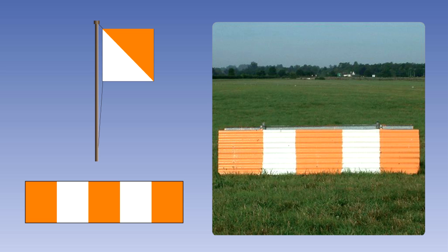At intervals along the boundary of an aerodrome, orange and white stripe markers are used to delineate the boundary where it is insufficiently conspicuous. Runway taxi holding positions are established on each taxiway leading to a runway in order to protect aircraft on takeoff and landing by ensuring that other taxiing aircraft and vehicles are held well clear of the runway and, where appropriate, outside the ILS sensitive area.